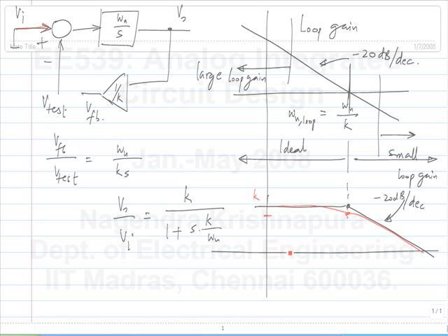Okay. So last time I said you have to increase the unity gain frequency of the integrator to make it faster, but of course the behavior also depends on the value k. So it's really the unity loop gain frequency that you have to increase if you want to increase the bandwidth, or basically increase the range of frequencies where the circuit must behave ideally. Okay. Is this clear?